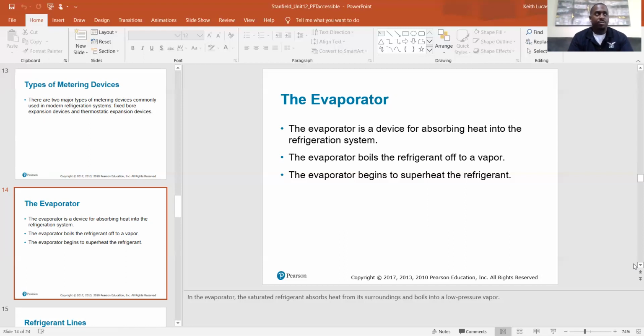If you're ever not sure which vent you're looking at, whether it's a return or a supply, you can always pull out a dollar bill and put it up against the vent. If it's a return vent, it's going to suck that dollar bill up against it and hold it there because it's drawing air in. If you put that same dollar bill in front of a supply vent, it's going to blow your dollar down because it's blowing air out. So the return is sucking air in.